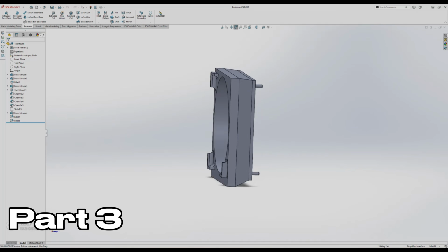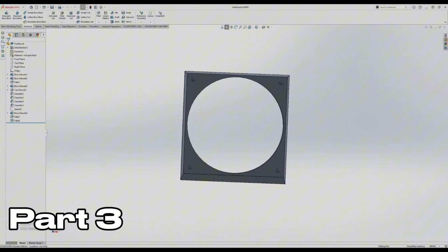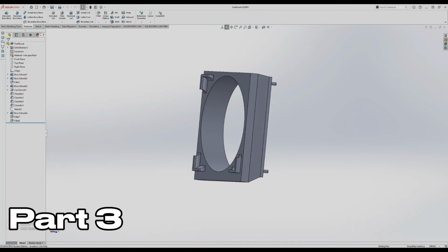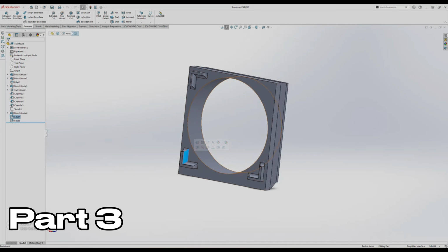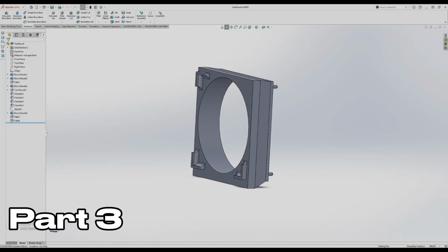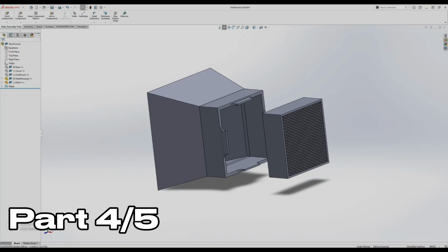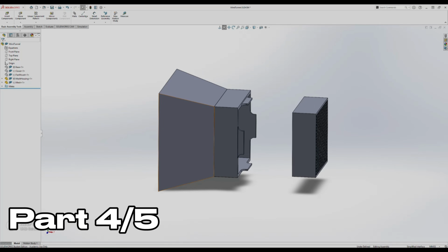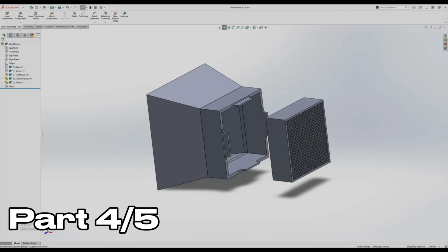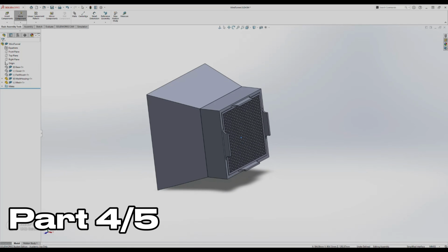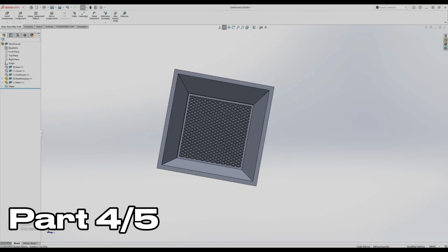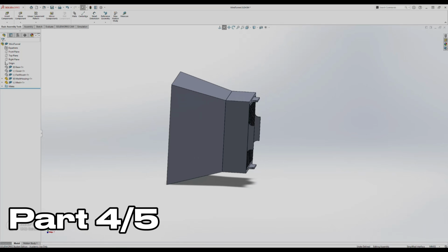The fan mount was the third piece, and like its name says, it's just a bracket that holds the fan. This was also my first attempt at a press fit design meant to slot in without any fasteners. The fourth and fifth pieces make up the intake section, a converging duct that steps down from a larger inlet to a smaller outlet paired with a printed honeycomb mesh block. Together, these are meant to condition the airflow into something more laminar, which is more useful for visualization.